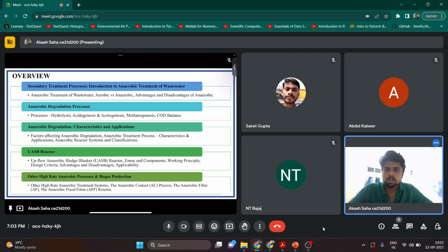So, we will quickly go through what are all the topics that have been discussed in week 7. I hope I am audible. So in week 7 we started looking at the anaerobic treatment of wastewater, the basic concepts related to that, and also we compared the aerobic and the anaerobic system, the advantages and the disadvantages. Then we moved into the anaerobic degradation processes where we learned the various processes related to anaerobic digestion, starting from the hydrolysis, acetogenesis, and methanogenesis, and at last we saw the COD balance.